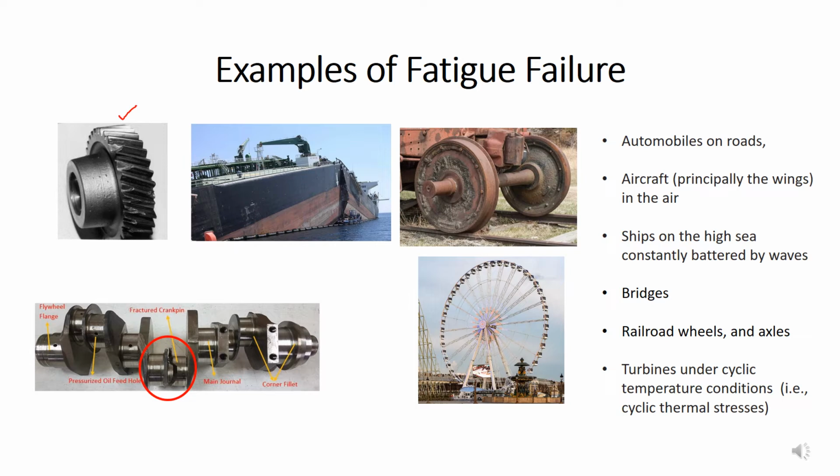For power transmission, gears mesh with one another. At high powers and low powers the rate at which the gears revolve differs, and during meshing they apply force over one another, and this force leads to fatigue loading of the gears. Here you can see the gears have been worn out, and this is due to fatigue loading.